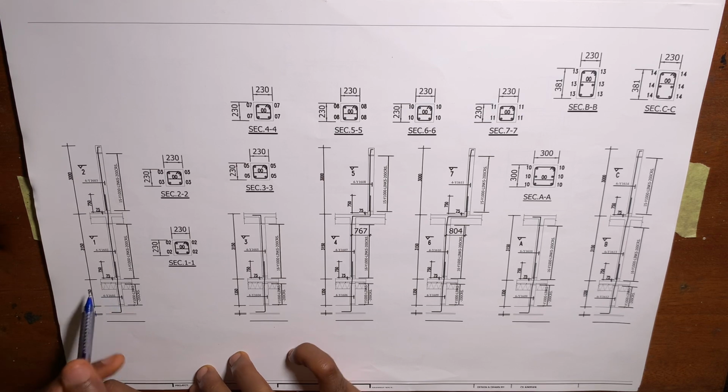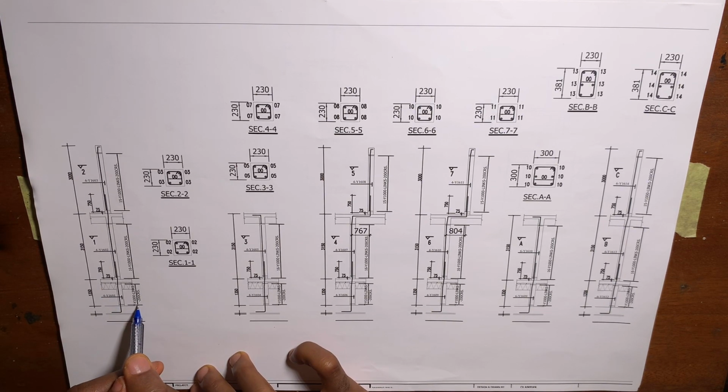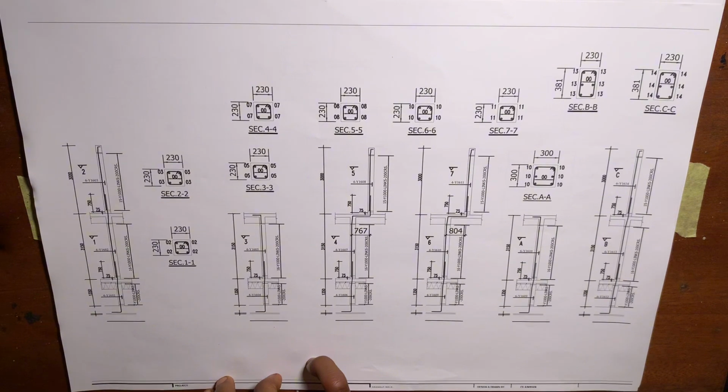Similarly, the links or the stirrups, that line says y10-00, that's bar mark 00, links at 200 center to center spacing. Now just on the line you can see there's a 7 there, so it means that the number of these links is 7 in number. That's what it simply means. The number of the links that will be lined from here to here is 7 in number at 200 center to center spacing.